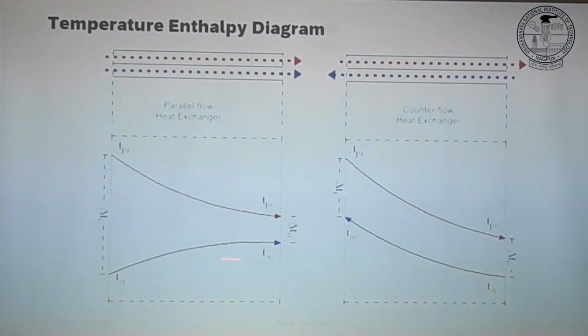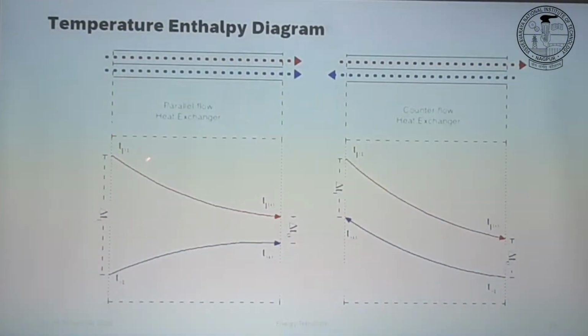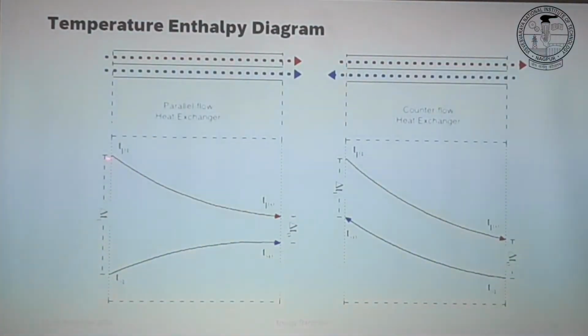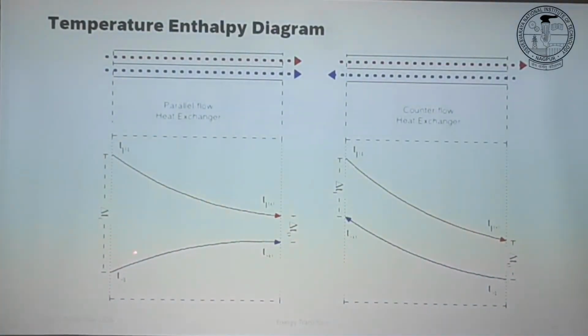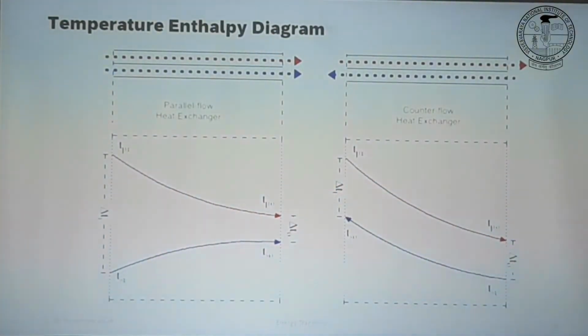Yes, number of passes. So you can increase here two pass, you can increase here also two pass. Like this. Means one shell pass, two tube passes. Now we have one shell pass, one tube pass. It goes here and here. It's one shell pass, two tube pass. It goes here and here, two shell pass. You can have two shell passes as well.